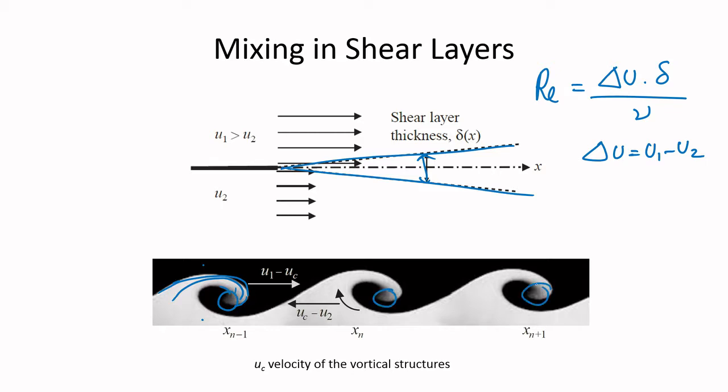So it is this type of roll up, vortex roll ups, that assist in mixing in high speed flows. Eventually there has to be diffusion at the smaller scales which mixes the two fluids, but the diffusion process is assisted by the creation of large species gradients, which is accomplished through the roll up of these different structures, which assist in creating large species composition gradients in the flow itself.